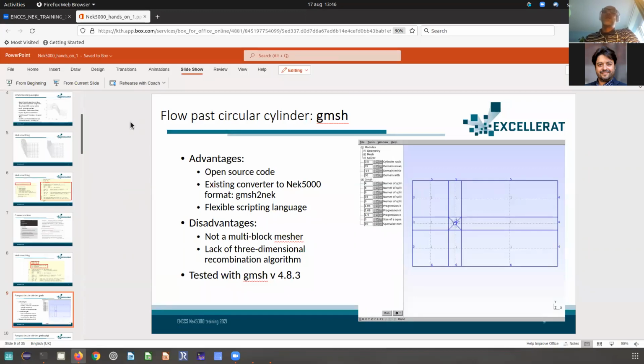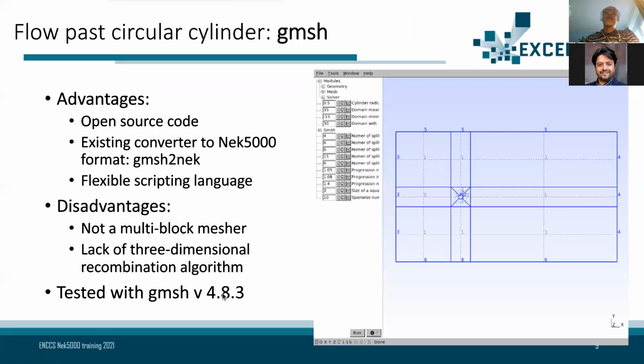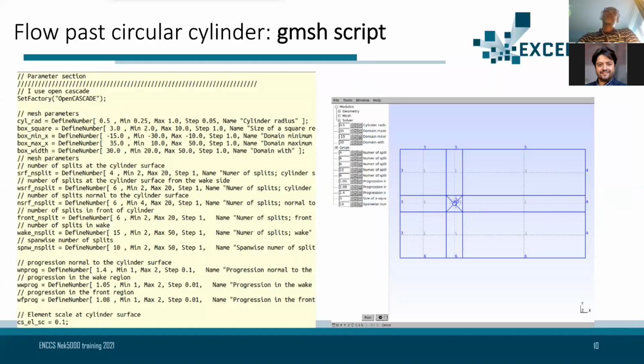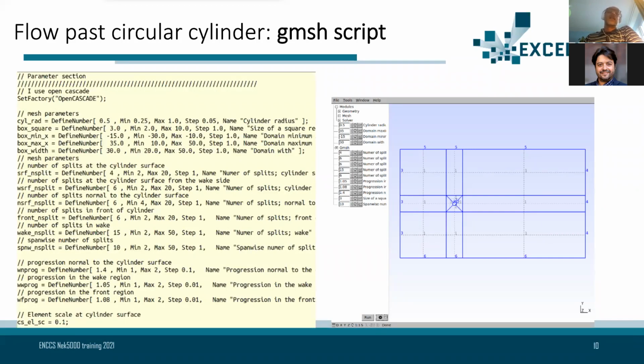But what about the mesh generation? The mesh generation is done by, in my case, I'm using this Gmsh 4.8 by running the script and executing the file with the ending .geo. So going very briefly through Gmsh, I will not add here a full description, but Gmsh actually has a pretty nice scripting language, which allows you to add multiple different variables, like here.